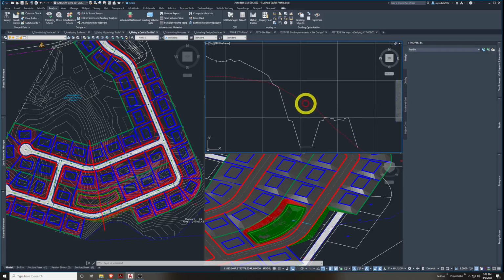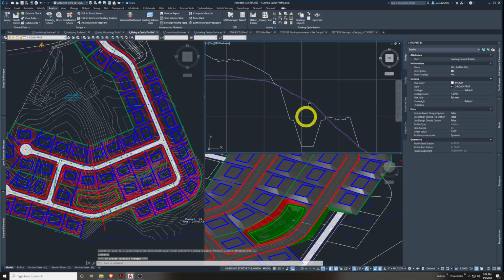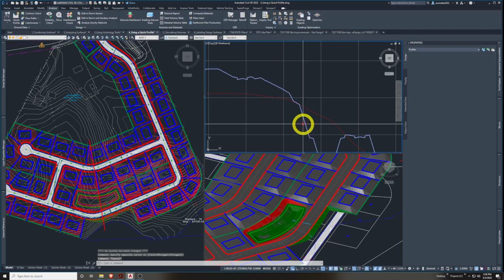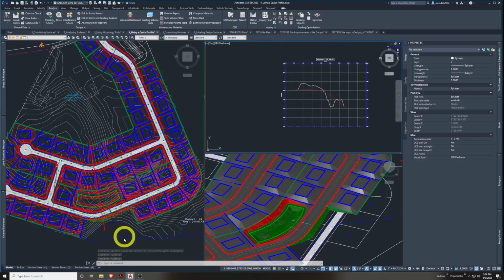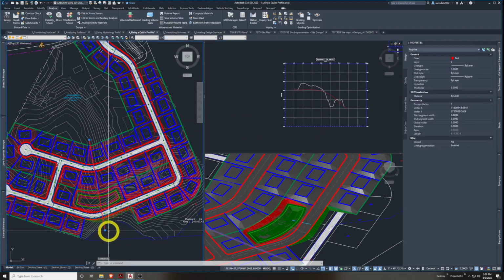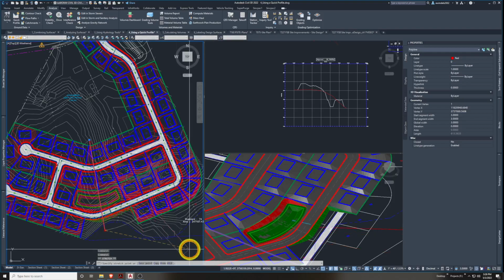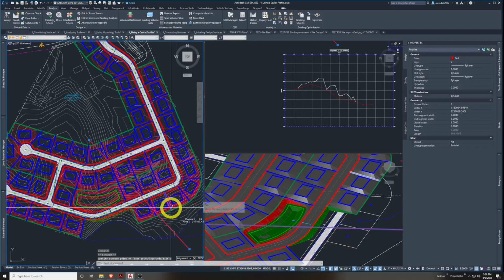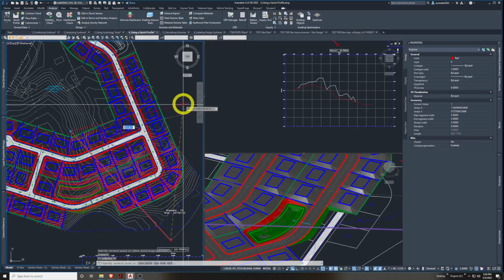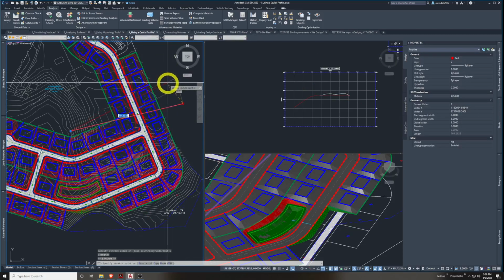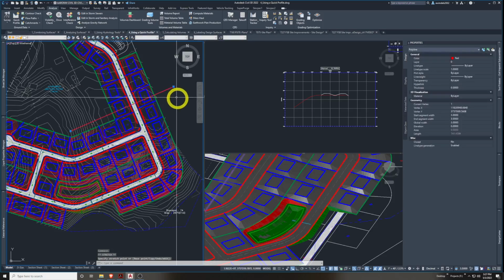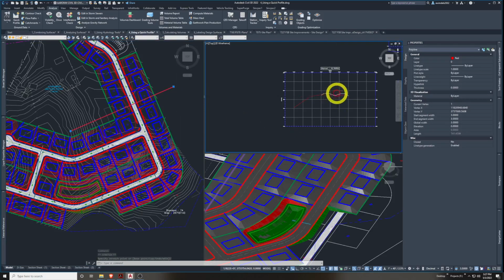So if you click these polylines, they have grips. Well, this red one doesn't exactly. They're more static, so they're surface profiles. So they're meant to be static. My mistake saying they're not dynamic in that way. But if we take this polyline, we move it, it will update my quick profile. So that's pretty nice. I can quickly check other areas, see if I like them, and the finished grade to existing grade analysis. See if that looks about right on the building pads to the road in the middle.